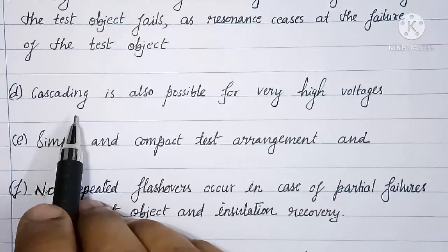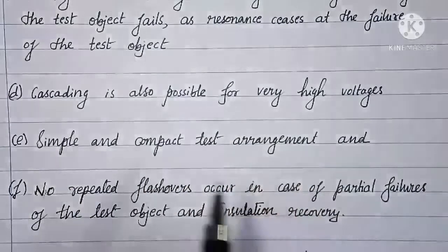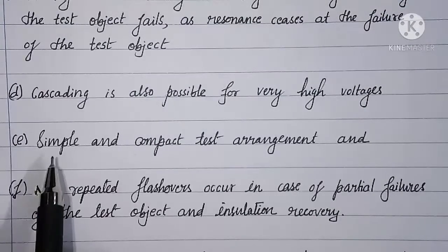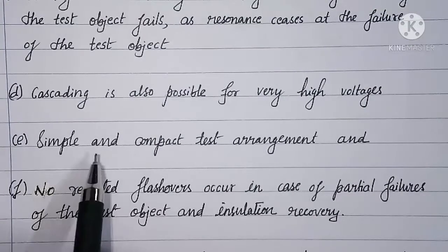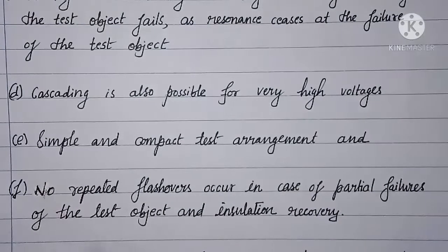Fourth advantage is cascading is also possible for very high voltages. If we need higher voltages, then we can go for connecting output of one transformer to another transformer and obtain the high voltages. The fifth advantage is it has simple and compact test arrangement, and the sixth advantage is no repeated flashover occurs